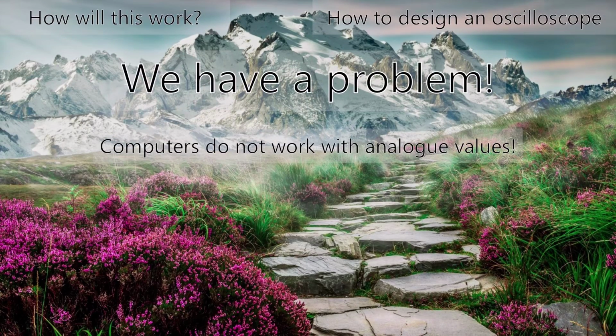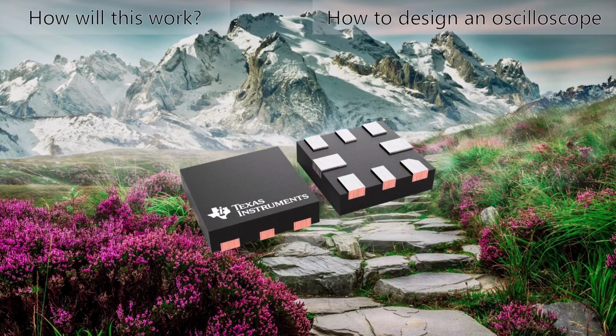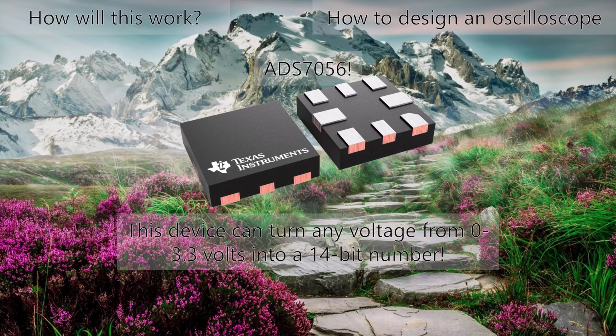So firstly, we have a problem. Computers cannot directly understand analog or constantly changing values. I present you an analog to digital converter, or ADC. This converts your constantly changing voltage from 0 to 3.3 volts to a nice, easily readable value for computers.